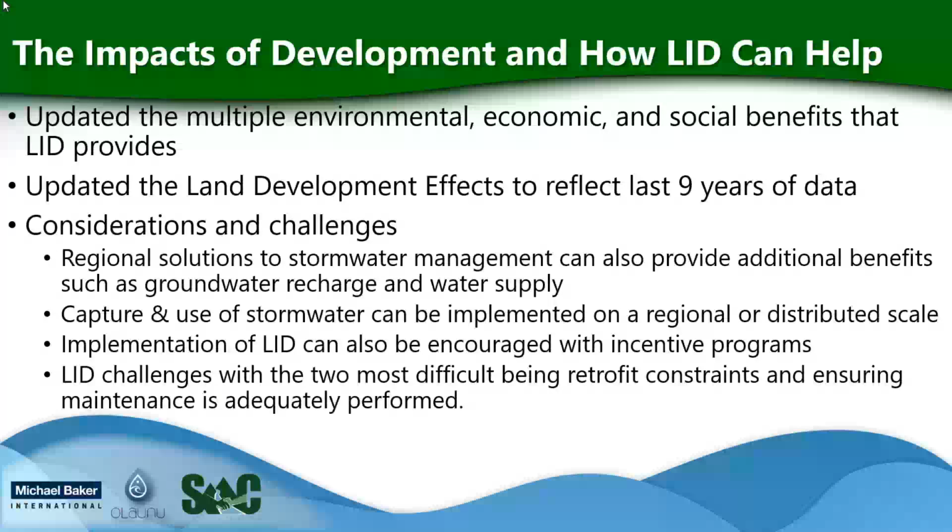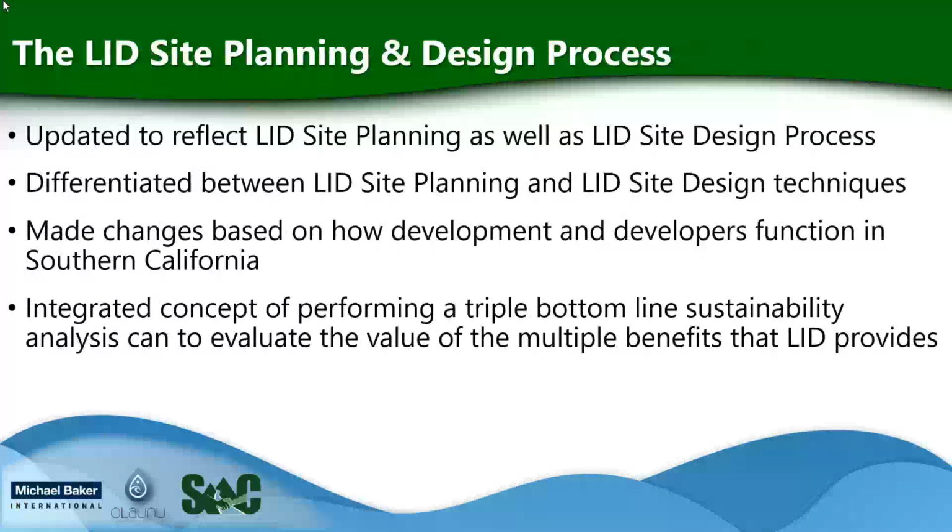As far as the LID site planning and design process, we've updated it to recognize that there is a difference between LID site planning as well as LID site design, with LID site planning focusing on preserving hydrologic functions and LID site design integrating structural design measures like green roofs and pervious pavement to help reduce the amount of stormwater discharging from a site and reduce the amount of impervious surfaces on a site.